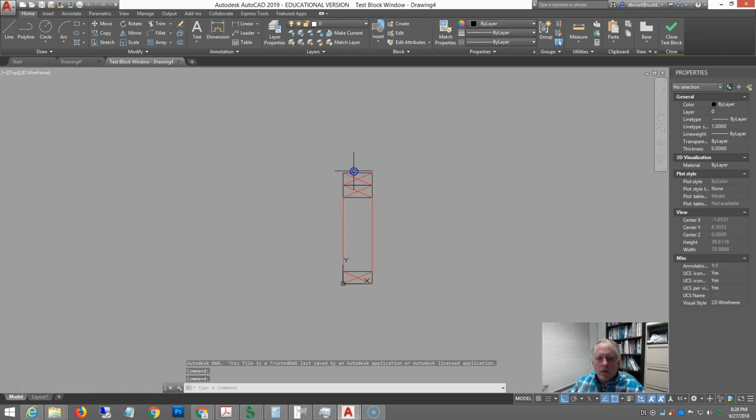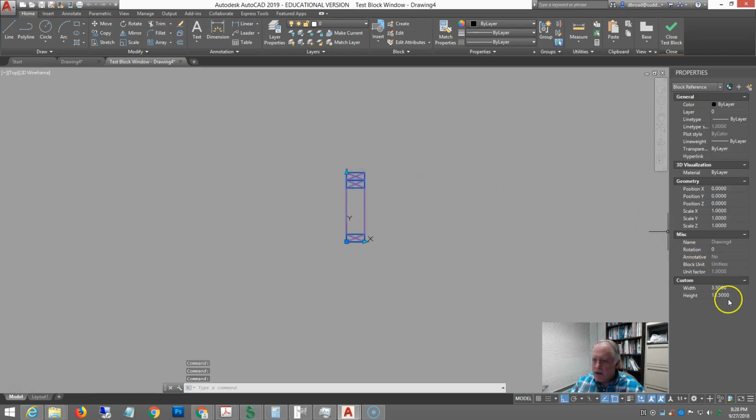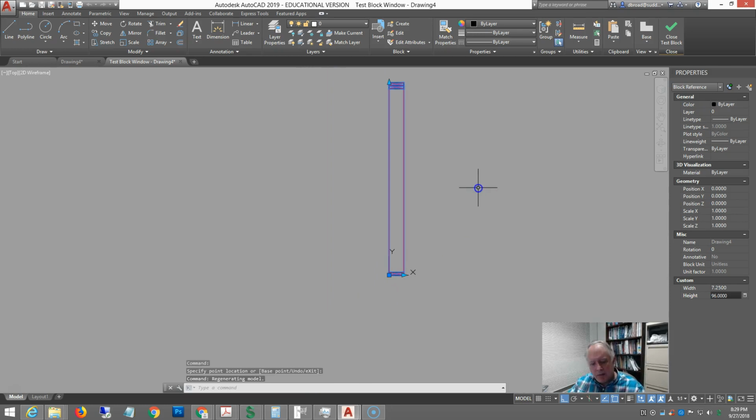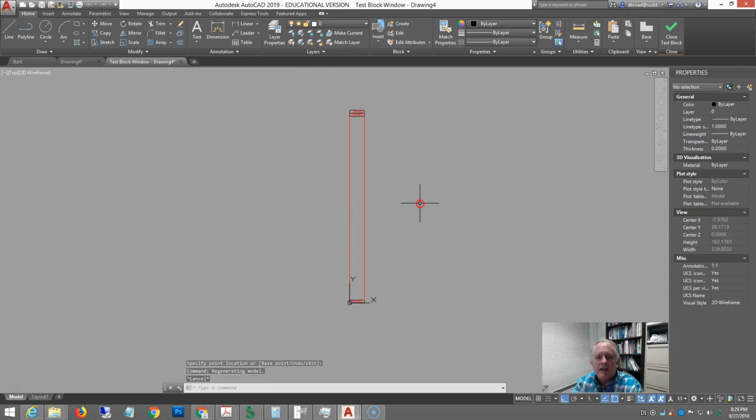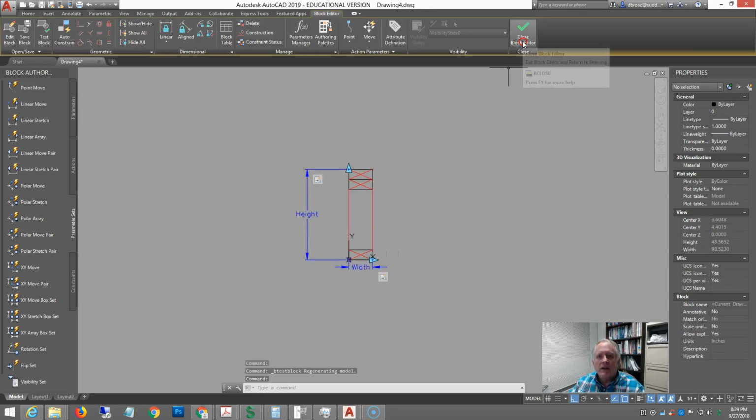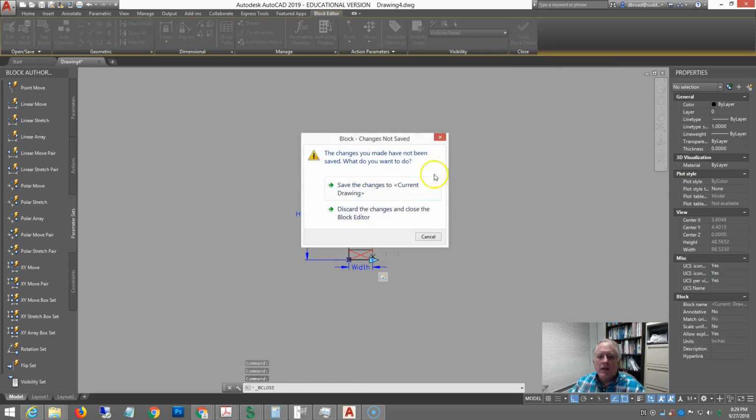So this height is going to start off at 13.5. You could choose a different height if you want. And I could choose an increment, but it's better not to. And then you could just always set a height over here, 8 foot. But now here I can try different stud widths. Now, if somebody really wants to create a 2x10 stud, you could add it very easily. When you're done, close the test block, and then when you think it's good, close the block editor.